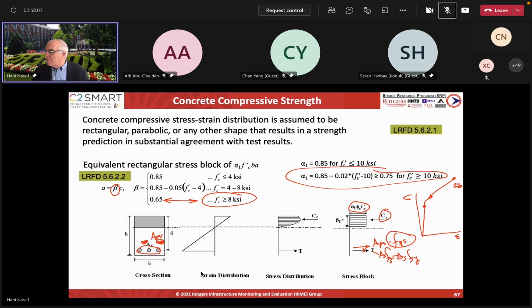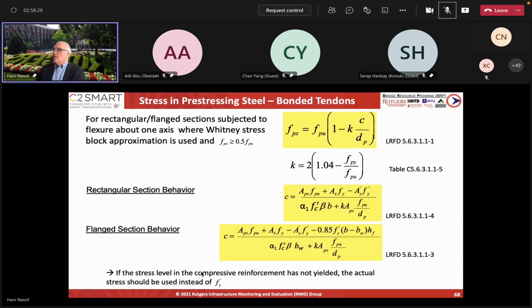If this is 270 here, the yielding might be about 230, 235, and then you pre-stress it up to the effective pre-stress, let's say 185, 189 usually. So in this range, it's elastic. But then when you start loading the pre-stressed beam, this stress starts increasing, and we need to know where. We need to know at what value it fails. So you need an equation for this FPS, for bonded. And that equation AASHTO is using is by the work of Professor Naaman.